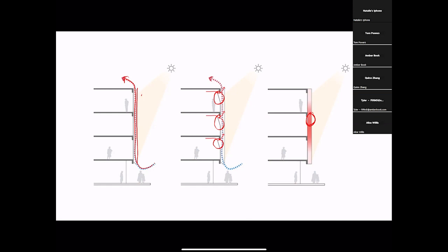All right, Natalie. Thank you for the presentation. Could you clarify? When I first saw the question for the class, I was like, oh, people use a double skin facade to create a convective loop so that it cools down the skin envelope of the building. But then it kind of threw me off when somebody asked about the convective loop being why it doesn't work. Yeah, so it creates a convection, but not a loop. A convective loop means it goes up one side and down the other, but we want it to go up and out, not up one side and down the other.